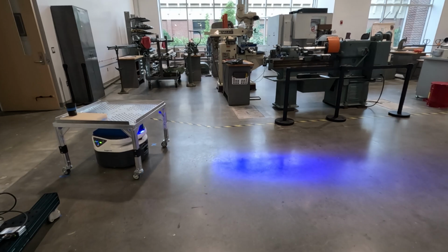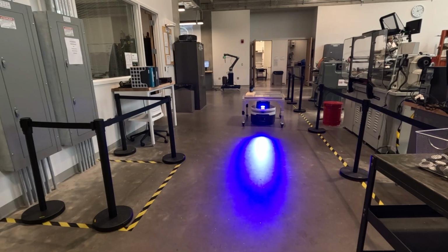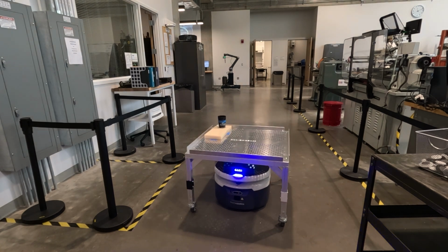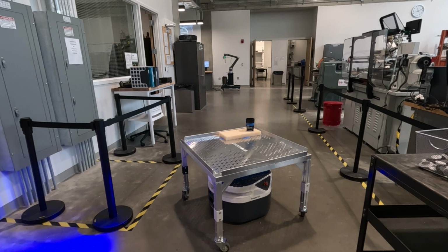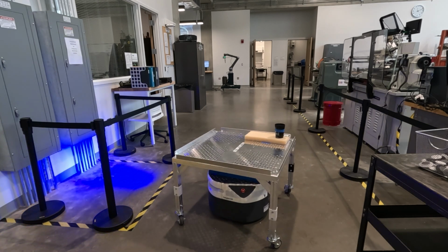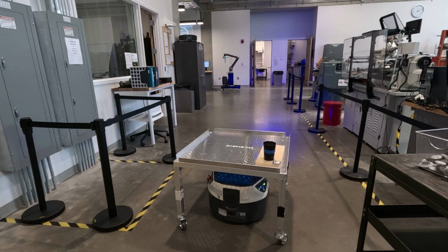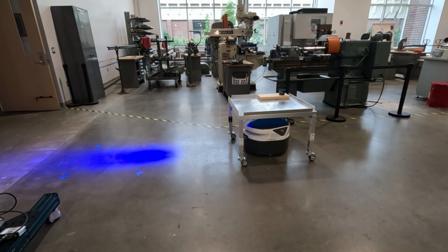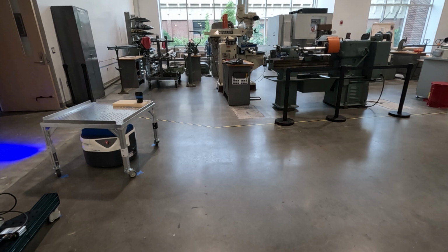Next, you will need to program two workflows in FetchCore. The first one will drive the AMR over to the manual station. You'll have to ensure that the AMR is in the right orientation so that the cup is presented to the operator at the station. And then the other workflow that you'll have to program will drive the AMR back to the Cobot, again ensuring that the cart is in the proper orientation so that the TM12 can pick up the cup.